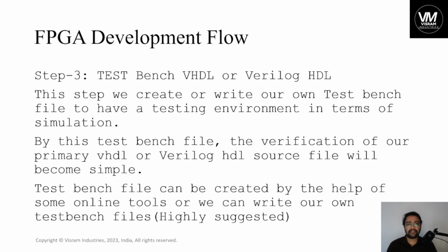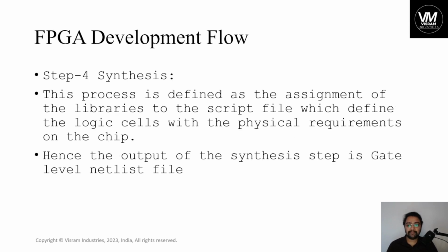The engineers who know test bench VHDL writing and scripting, or who are familiar with Verilog HDL and also write test benches, have more chances of getting recruited. Then move on to the next step, which is synthesis. In the synthesis, according to the physical requirements of the design, all the library cells that are to be enabled on the FPGA chip are connected with the functionality that you have written in the HDL script.